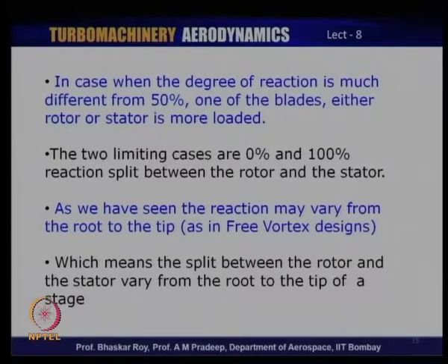This reaction now varies in free vortex or near free vortex, and would vary substantially from root to the tip of the blade, which means from the root to the tip of a stage, the split between the rotor and the stator would vary.